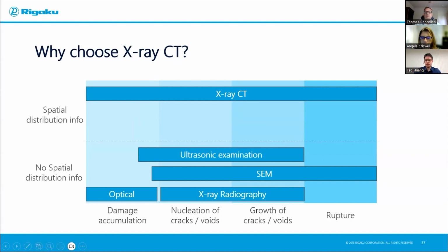So let's just say there's a crack in your product, using ultrasonic examination. It is very different if the crack is at an insignificant edge or corner of your product that's never going to experience any load, compared to the same crack at the dead center of where the load is supposed to go, right? You want to see where they are. Ultrasonic examination cannot really do that as effectively. Well, X-ray CT can; it lets you see it directly.